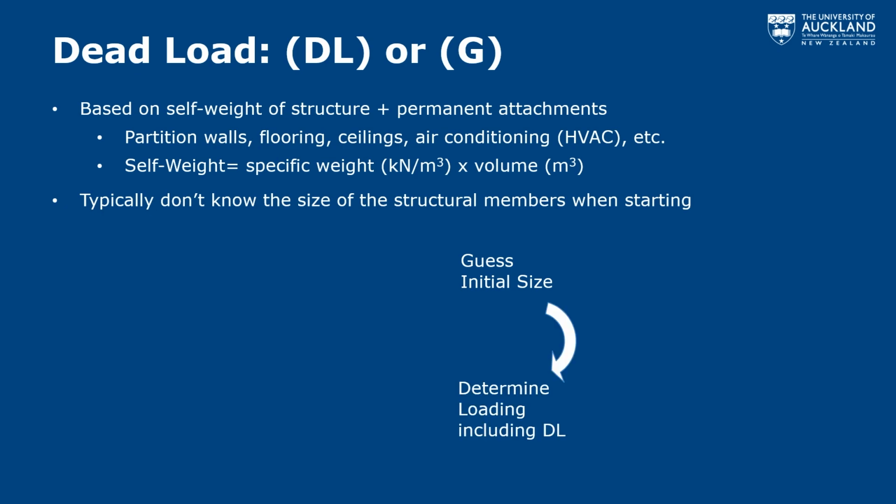But no matter what, you make an initial guess, and then you have to find out, well, what's the loading? So if I say I have a size of an element, say I want something which is rectangular, 100 millimeters wide and 200 millimeters deep. Then I need to check what the loading is of that self-weight for the material that I'm using and see what additional demand the self-weight puts on. And then I'll analyze that little statics problem that includes the imposed load as well as its own self-weight.